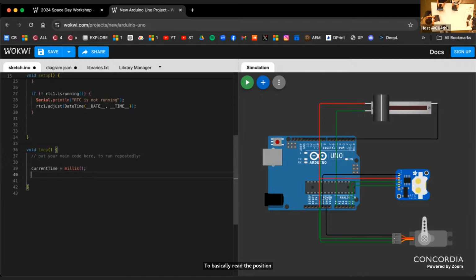Here's the thing with embedded. You can't just code simply on what you see. In embedded programming, there's a huge focus on reading documentation and making sure of what you're reading. Usually in embedded programming, you constantly have to look at the board, and that's what we did. As I said, I knew that the 1.6 line is the SDA line and 1.7 is the SCL on the MSP board, but I had to go through documentation and find out which pin it is, because there's a lot of pins, and I don't know what any of them do. So you got to look at the data sheets and learn.